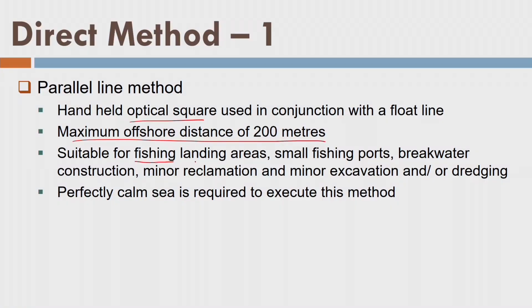What is the reason? I want to collect data which is very dense at very regular intervals near the shoreline and not away from it. Secondly, the assumptions of low water current and no wind velocity are appropriate there. That is why this method is restricted to 200 meters from the shoreline. It is only suitable for fishing landing areas, small fishing ports, some breakwater construction, minor reclamation and minor excavation or small dredging purposes, and a perfectly calm sea is required.